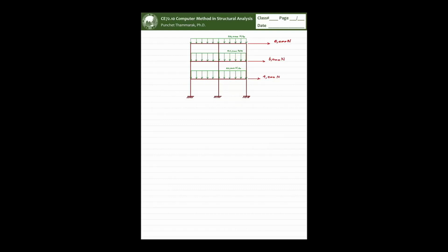I used to see some work. Analysis is done, apply the slab using the shell. You have the frame structure, the slab is supposed to rest on the beam, right? Transfer the load to the column. Get the analysis result. I check, okay, how does the slab deform? Okay, the slab deforms. How about the beam? The beam doesn't deform. Things like this. If you don't check logically, look at your result and see the logic.